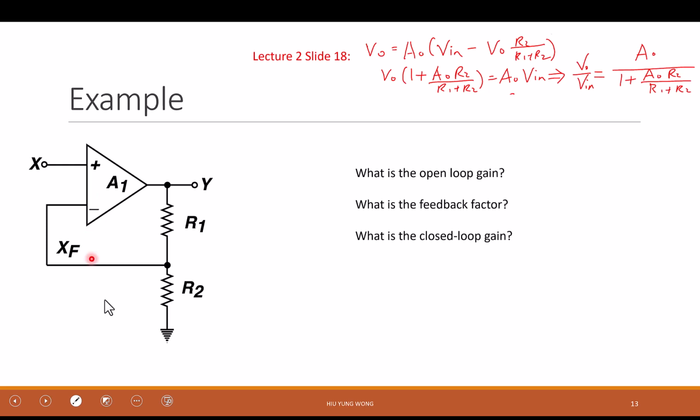Many of you were able to tell me in the first class. This is just an op-amp, a long inverting amplifier. Don't think about feedback yet. That's what we studied earlier, and we used KCL, KVL, and the op-amp property to derive this equation when A0 is not infinity, a finite gain. Now I can treat this as a feedback circuit, and that will be very fast.